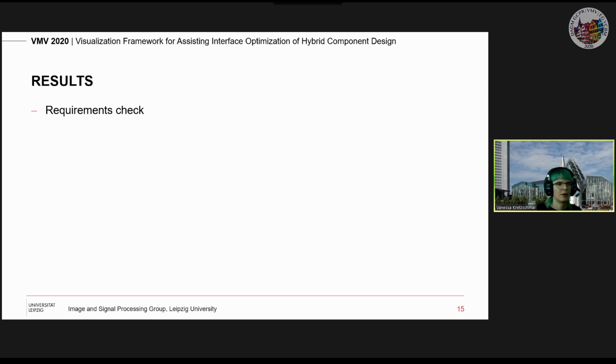And coming to the insights our tool provided, we learned that placing a big number of pins increases the amount of force the specimen can transfer. However, the engineer does not need to cover every possible pin position, since we found an optimum with fewer pins than maximal possible, which translates to saving materials and therefore saving some costs.